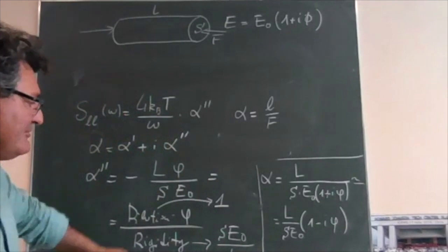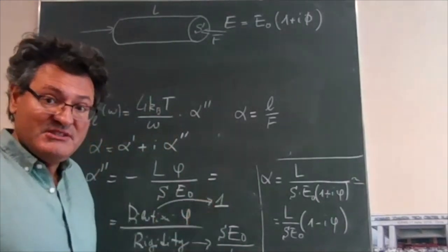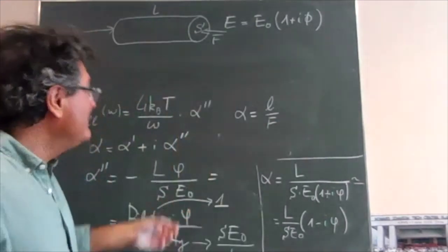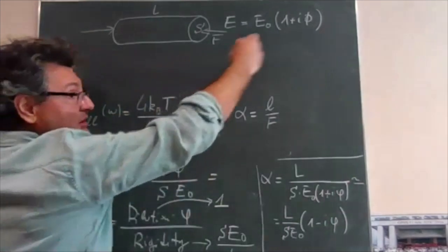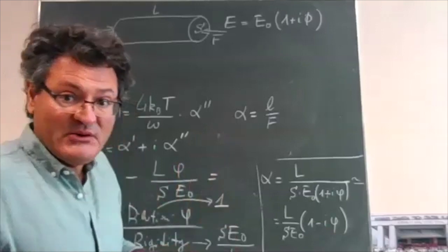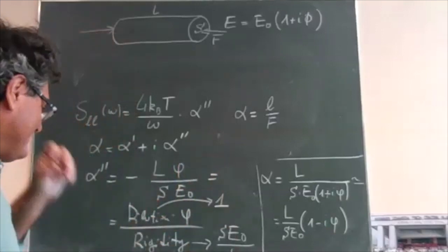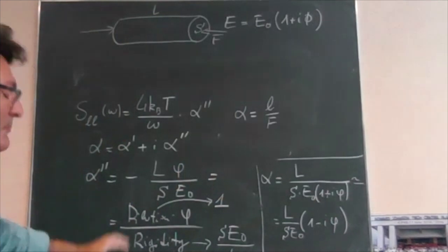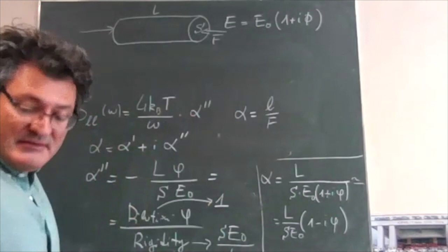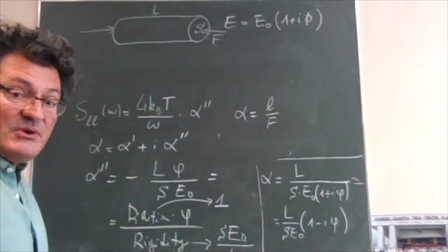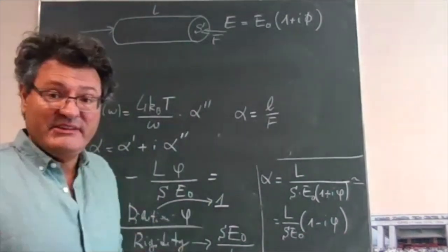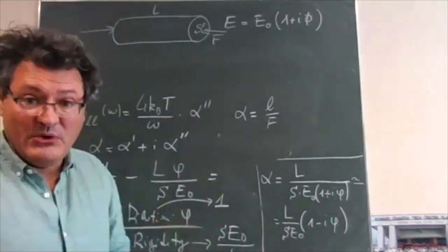If you want to decrease the rigidity, so in order to make the thermal noise higher, we need to have a really long and really thin beam. In this case, the thermal noise increases. The opposite, a thick and short beam, corresponds to a system that is quite high in rigidity, so low in thermal noise.